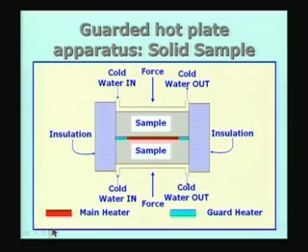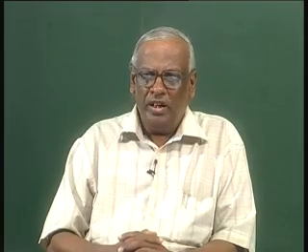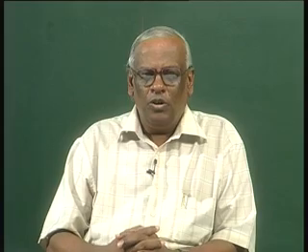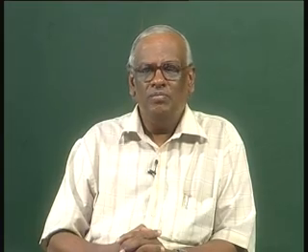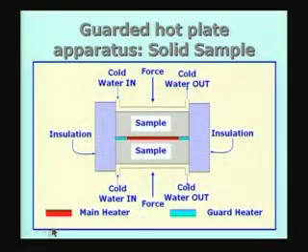So, let us look at one simple arrangement. In fact, earlier when we talked about the measurement of heat flux, we already looked at the concept of the guard, and if you recall from our discussion earlier, a guard heater is going to help in reducing the losses in a transverse direction, and therefore make the temperature field or the heat flux one directional or one dimensional.